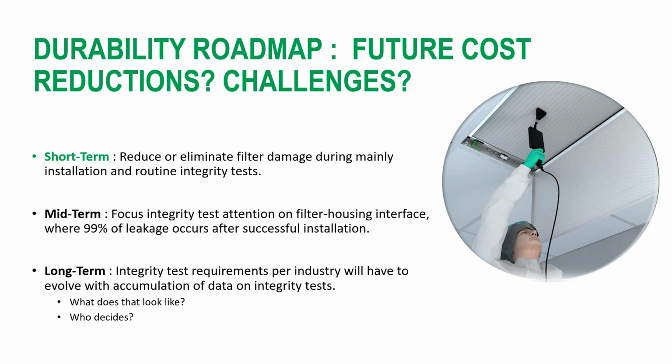And obviously the point of sustainable labs is to introduce different, more sustainable solutions, but it may ask you to step out of your comfort zone for a second. We've seen that some new medias can really lower your pressure drop and maintain their integrity, even if installed by a new technician who's never handled a HEPA filter before and is a little rough with it. EnerGuard, for example, can survive that kind of impact.